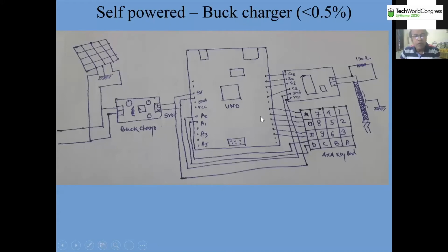And the display mode: when you put that master in display mode, it will get data from all the slaves. The slaves will give data with their address and then 0 to 1023. This is the 4 bytes. This is the payload. In this 12 bytes, that depends upon how many address bits you are using.